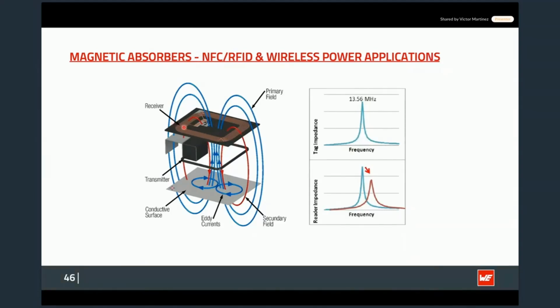And that material that I'm just remarking now is actually an FSFS, or a ferrite sintered sheet. And they are really commonly used in these kinds of applications, mainly because once you are designing your NFC antenna, you are normally designing it in a perfect environment where you are not thinking about, for example, the battery from your phone, or maybe the metal case from the housing, or maybe the metal case from the door or from the wall where the device is going to be placed.